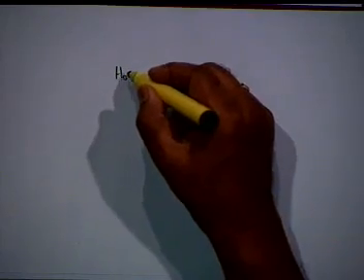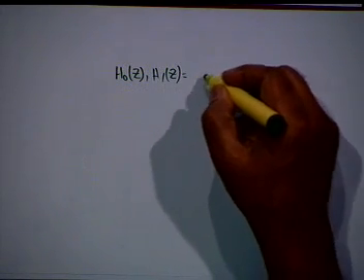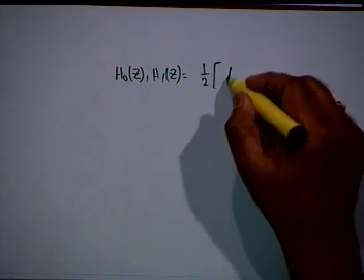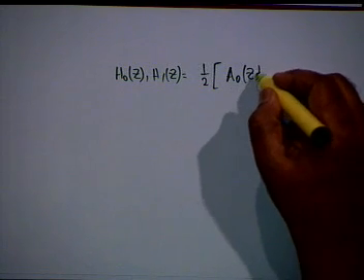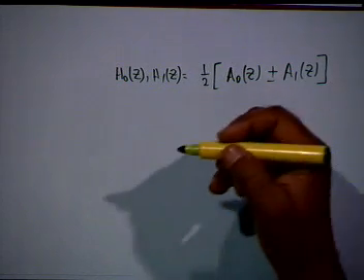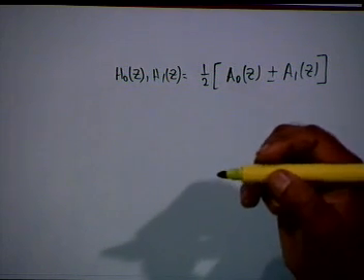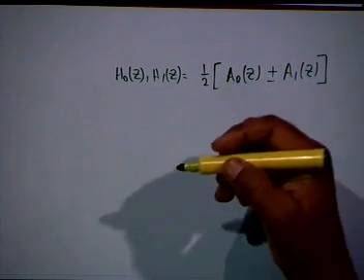In the last lecture, we showed that these two transfer functions H0(z) and H1(z), which are half of the sum and difference of two all pass functions, form an extremely important delay complementary as well as all pass complementary as well as power complementary pair of functions.